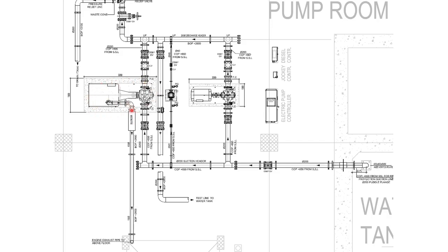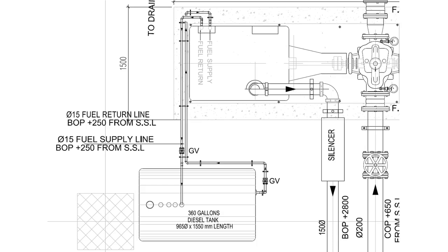10th step. So after determining the exhaust pipe sizing based on derate factor calculations, position the diesel tank, size the piping with valves from diesel engine to the fuel tank accordingly.